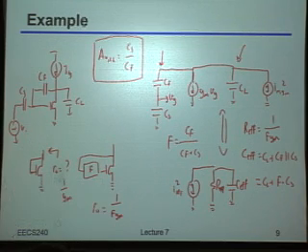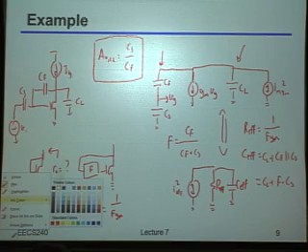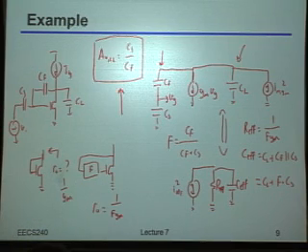Exactly. So just like we had gone through the example with a resistive feedback amplifier, notice the gain you apply to the signal is different than the gain you apply to the noise. Right? Because the signal is CS over CF, and the noise is by that 1 over F factor. And that 1 over F factor is always going to be higher. Okay? Does this make sense?